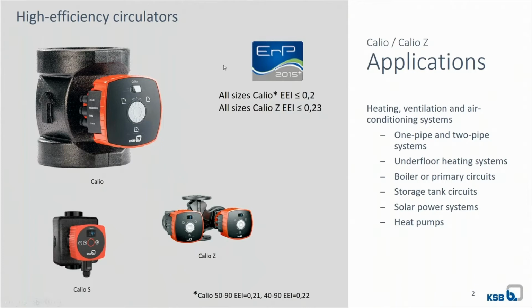On the slide, the EEI, Energy Efficiency Index, is named here sometimes, and it's important to sell this product. So that means if you want to sell a product or a pump, especially this pump, the energy efficiency index must be below a certain value. This is 0.23 in this case for heating pumps.